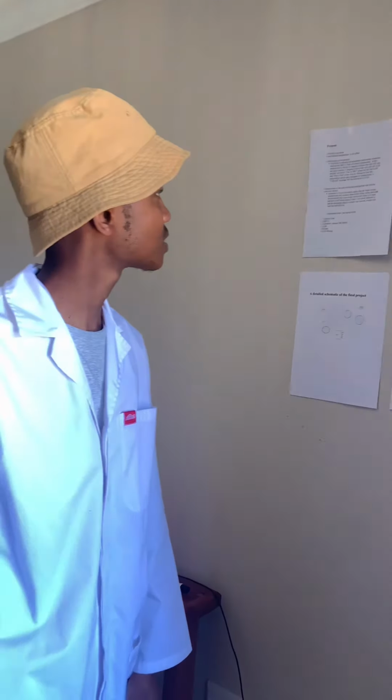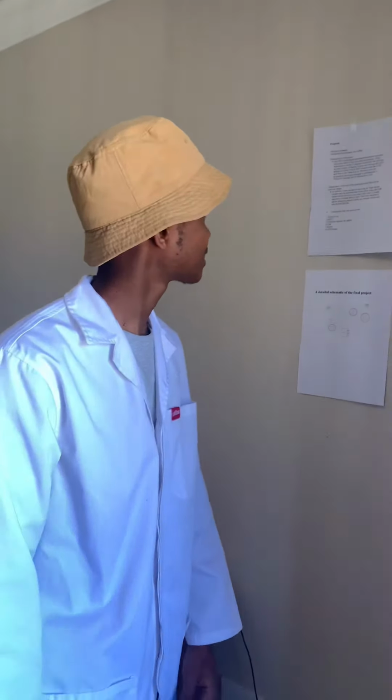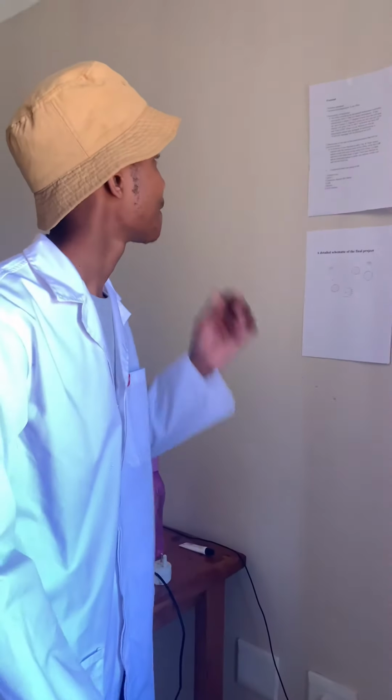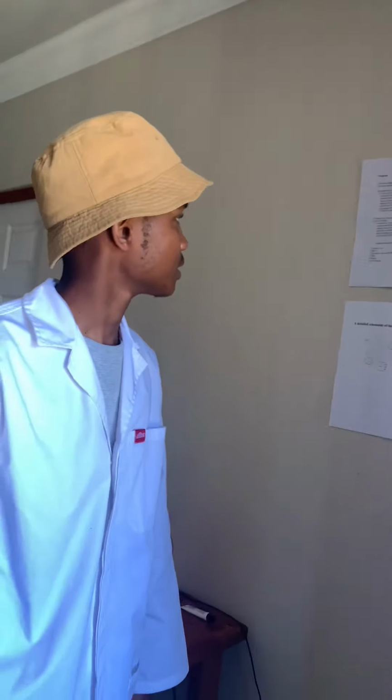Whenever the temperature sensor gets damaged, malfunctions, or fails to read any readings in the room, a failed message will be displayed on my LCD. In addition to this project, I have decided to add a day and night sensor that will detect whenever it is dark and whenever there is light. When there is light, the LED should be off, and when there is darkness, the LED should turn on. And also, we have an ultrasonic sensor which will detect any motion outside the premises.